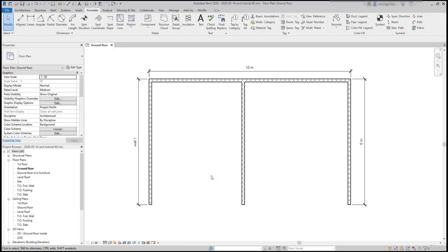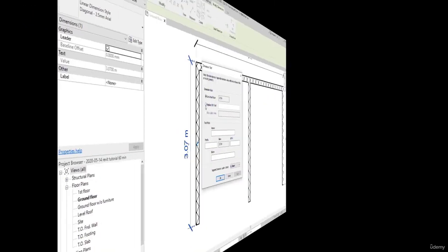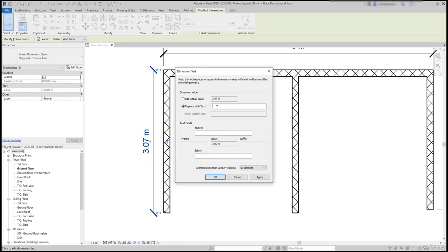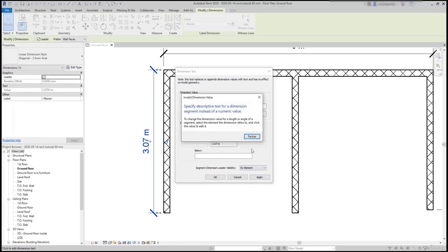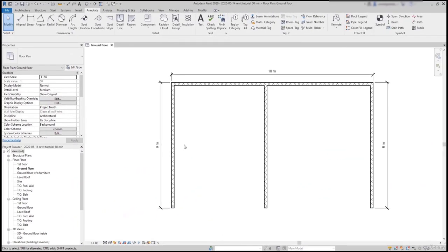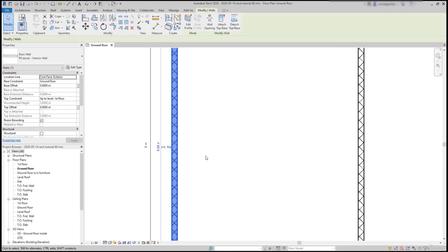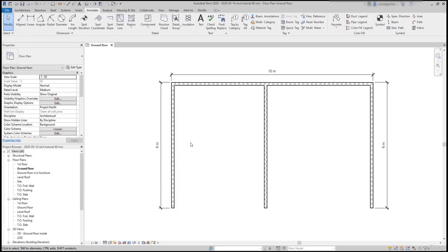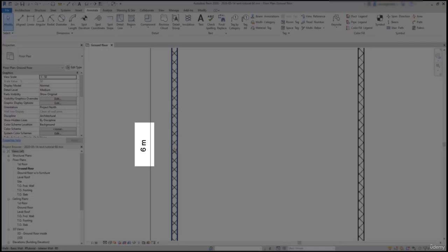But keep in mind, if I want to choose or change the actual value to an approximate number, the program doesn't let me do it. It says that I cannot replace a value with a different value. Basically, to modify the length of this wall, I have to select the wall first and then click on the dimensions in the same way that I do for temporary ones. Notice also that when the dimension is editable, the color changes to blue.